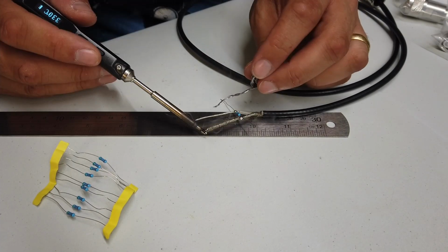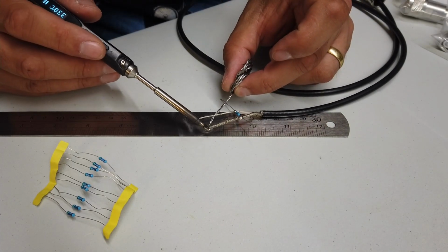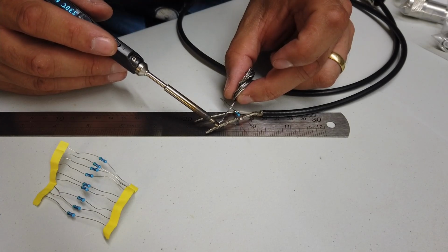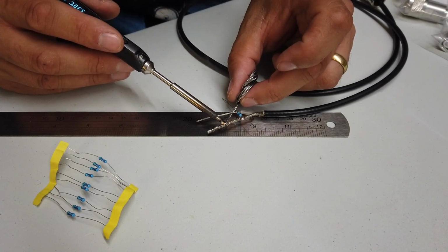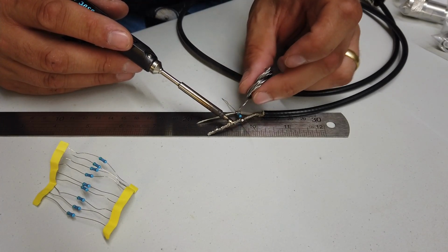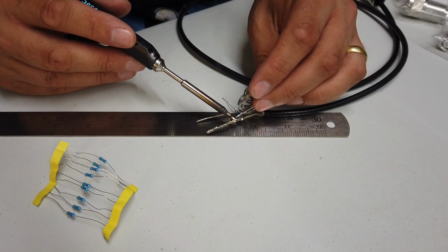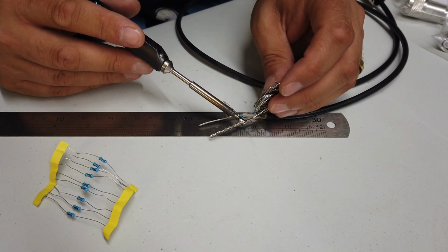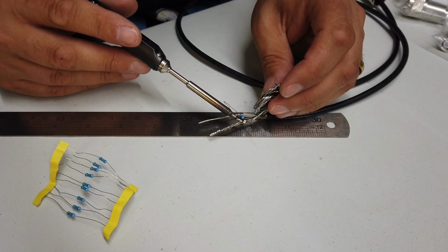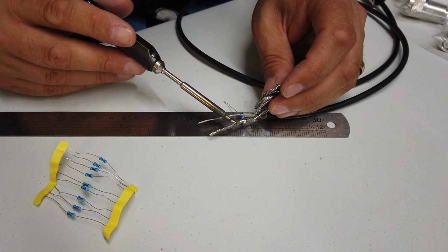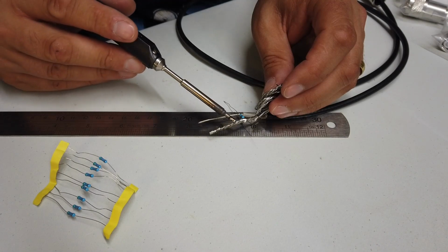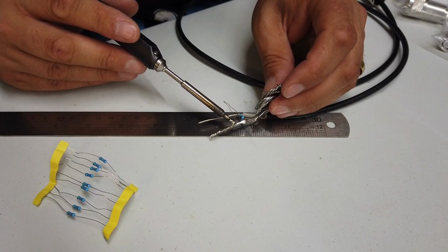which is sort of important. Anybody that's going to be doing tests on any type of radio transmitter should probably have a dummy load that matches the impedance output of your radio transmitter. And in my case, the impedance output of the radio transmitter is 50 ohms.